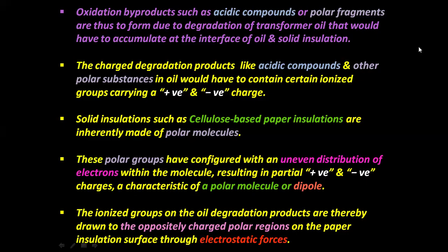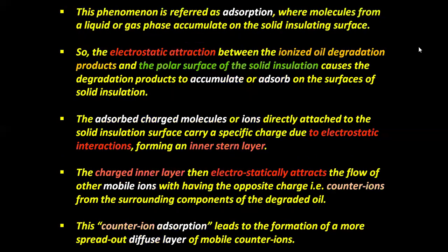The ionized groups on the oil degradation products are drawn to the oppositely charged polar regions on the paper insulation surface through electrostatic forces. This phenomenon is referred to as adsorption, where molecules from the liquid or gas phase accumulate on the solid insulating surface.